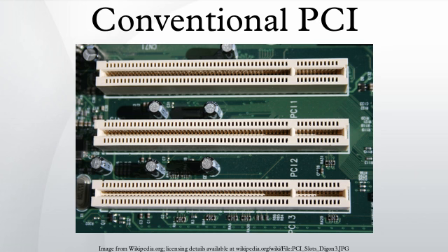Apple Computer adopted PCI for professional Power Macintosh computers in mid-1995, and the Performa product line in mid-1996. The 64-bit version of plain PCI remained rare in practice, although it was used, for example, by all G3 and G4 Power Macintosh computers. Later revisions of PCI added new features and performance improvements, including a 66 MHz 3.3V standard and 133 MHz PCI-X, and the adaptation of PCI signaling to other form factors. Both PCI-X 1.0b and PCI-X 2.0 are backward compatible with some PCI standards.